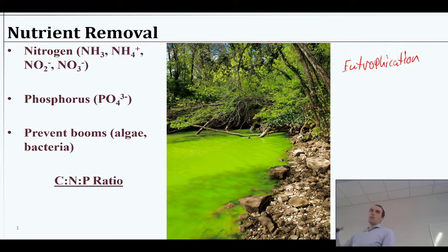So BOD then is not the full story. If we have a bunch of nitrogen or phosphorus, we could have some serious problems. And you'll see this pretty frequently with agriculture runoff. If you see a pond that's on some sort of agriculture farmland, chances are they sometimes will have algae blooms, just given the situation of that local environment.